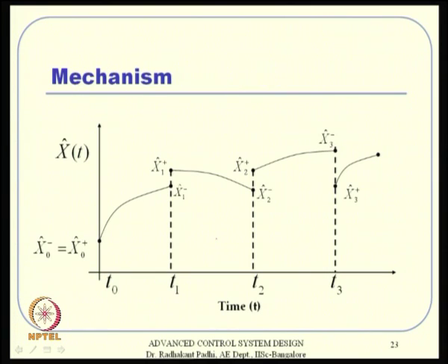And this is what I was talking about earlier, this prediction correction mechanism is what is popular here. Assuming some value at t0, I will be able to predict in a continuous time manner, using any numerical scheme, not necessarily zero order hold. You can use any continuous time propagation expressions to predict this. Once I predict, then the sensor information is available, and I will be able to correct it.